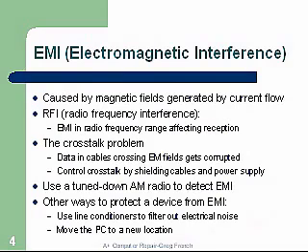EMI, electromagnetic interference, is caused by magnetic fields generated by current flow. Again, motors are probably some of the most common causes of EMI. Now, RFI, that's radio frequency interference. Radio frequencies can come from a lot of different sources. We can have microwaves, cell phones. Then there are crosstalk problems. Crosstalk is data in cables crossing, so we have fields that actually influence each other in the wires, and this can corrupt our data and cause problems.